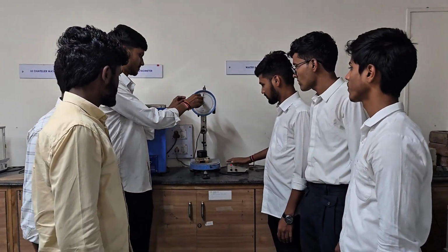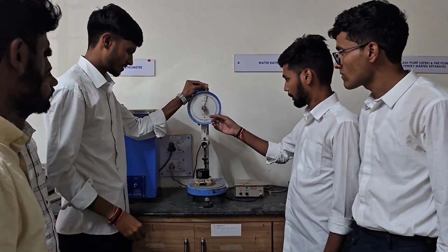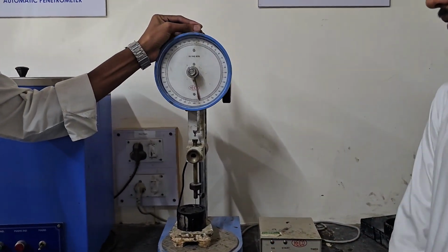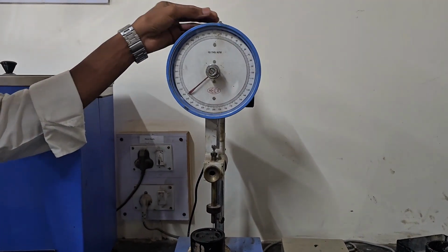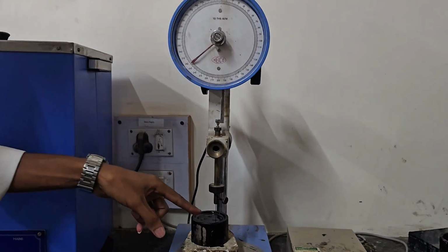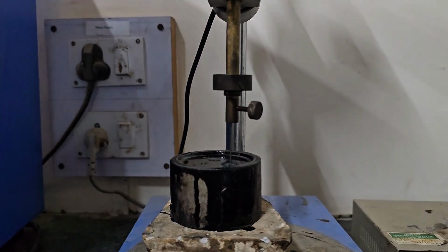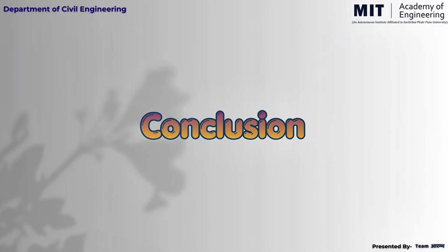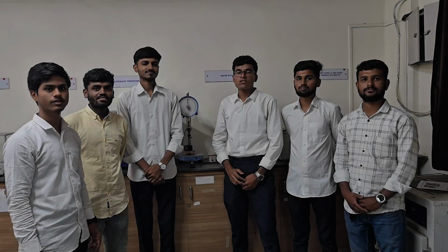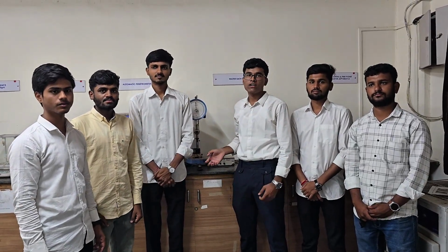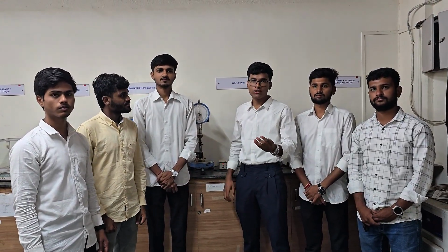As per standard practice, each test point should be at least 10 mm away from the previous point to avoid overlapping effects. The test is repeated at different locations and the average value is calculated for the sample. So we demonstrated the penetration test of bitumen practical in various parts like introduction, methodology, process.